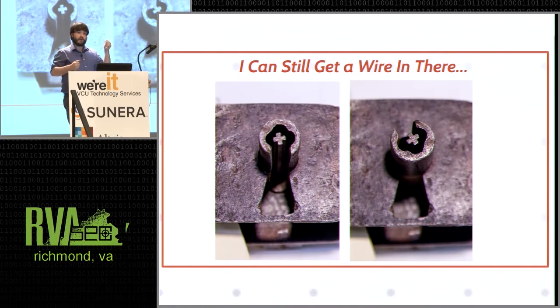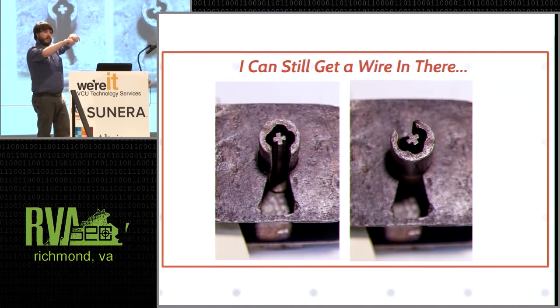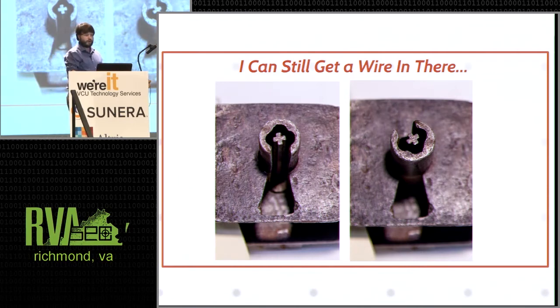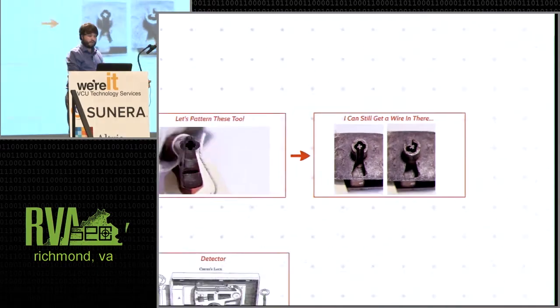So they invented the curtain. And the curtain actually ends up being really important for lever locks as well, which we'll get to in a little bit. But the curtain covers your key, and then as you turn the key, it continues to cover the keyway. So that if you're getting in there with a wire, as you begin turning, that whole thing will turn with you, whatever tools you're trying to use, and it just closes off important parts of the keyway from you. Curtains became much more elaborate with the lever locks and much more effective as well.